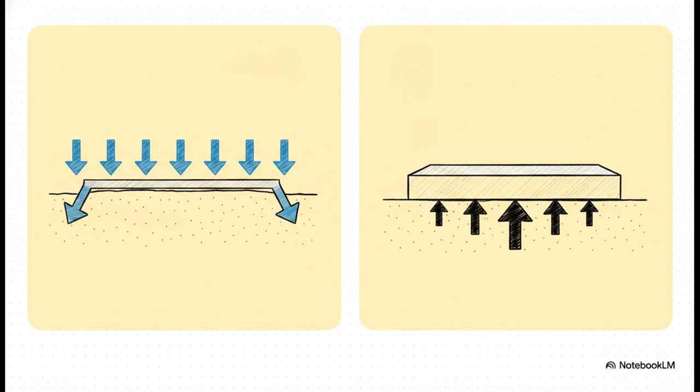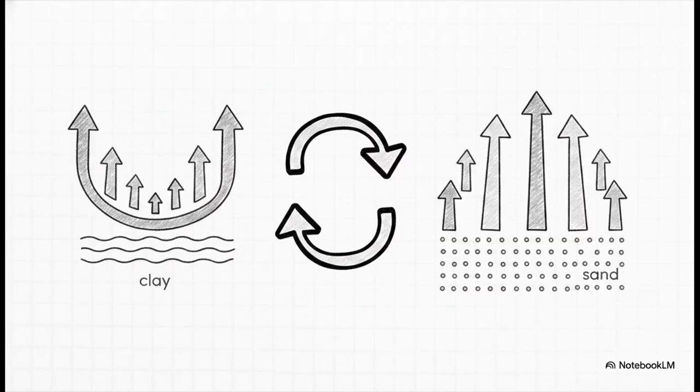Now look at the rigid foundation in sand. Just like before, a rigid foundation forces a totally flat settlement. But to actually achieve that flat profile in sand, the contact pressure needs to be higher in the middle and much lower at the edges. This creates a parabolic or dome-shaped pressure distribution, and this brilliantly illustrates the absolutely wild reality of soil mechanics.